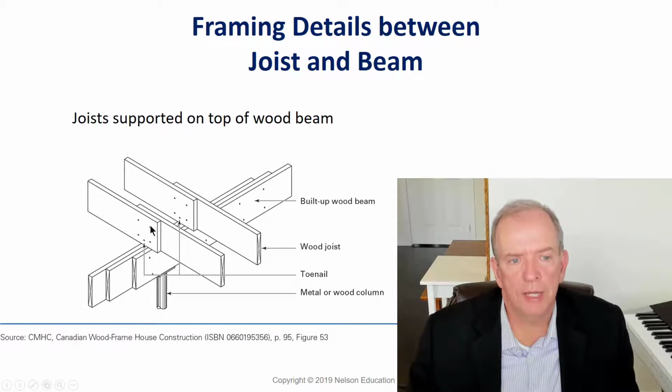So they lap over side to side. That's the quickest way. You don't want the joist to run too far past the support, right? So within about 2 or 3 inches, you want to stop them. Some framers, again, just run them long, because you could have a joist that's 10 foot 2 and you run it long, because it's a 12 footer, you had to buy a 12 footer.